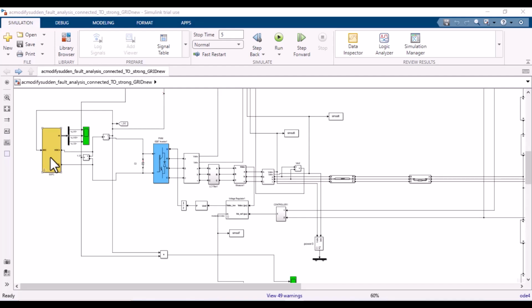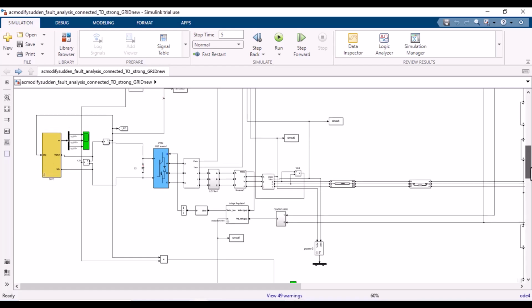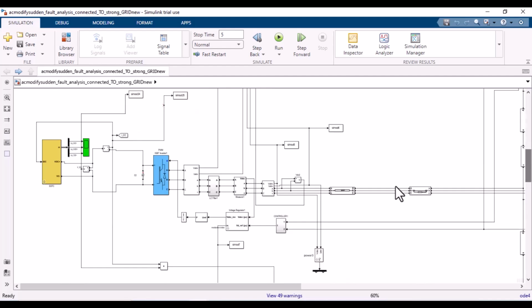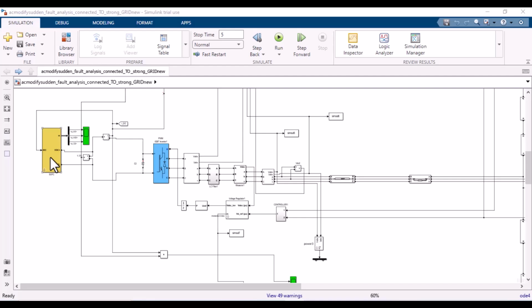Shunt filters can be connected in parallel with the system to absorb the harmonic currents. Series filters can be connected in the power line or on the transmission line to block harmonic voltages. Notch filters can be used to pass or attenuate certain frequencies, so they can behave like band stop filters. Active damping filters can be used in dynamic systems, using control algorithms, a type of control algorithm that can suppress the harmonic resonance.